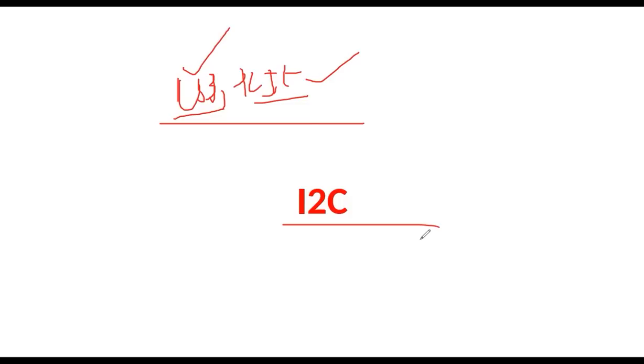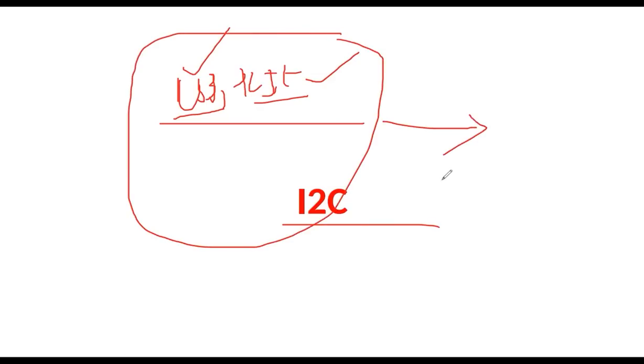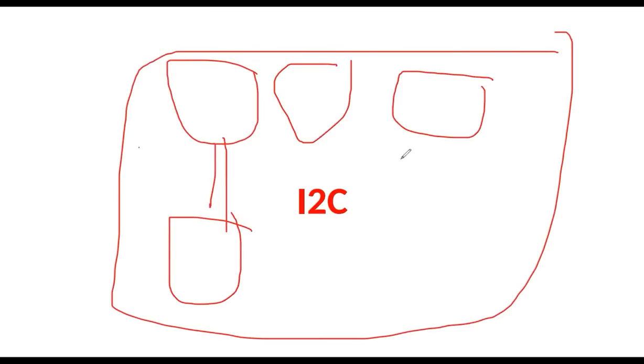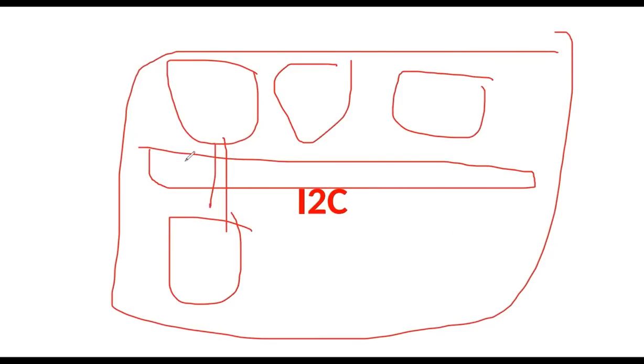And not only communication, we have the peripheral bus protocols. These protocols work under serial communication. Serial communication means all the data will be sent serially, one bit at a time. Whereas bus protocols are the AMBA protocols. Suppose in our SoC there will be a lot of IPs. If you want to connect one IP to another IP, we will use one bus, a very big bandwidth bus.